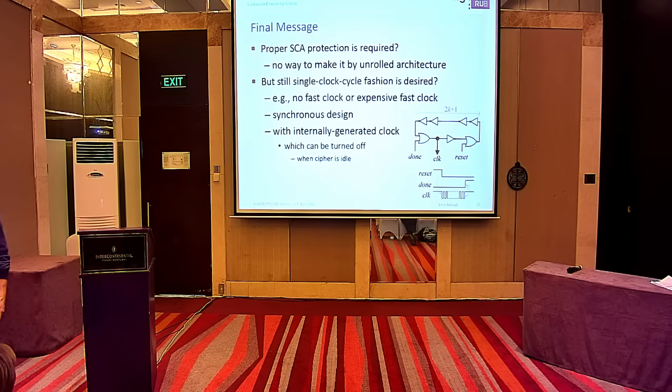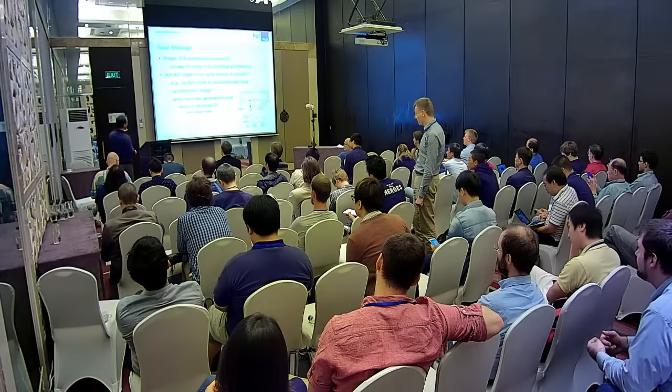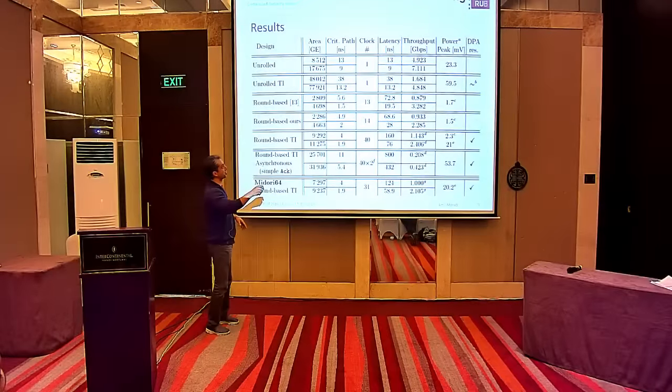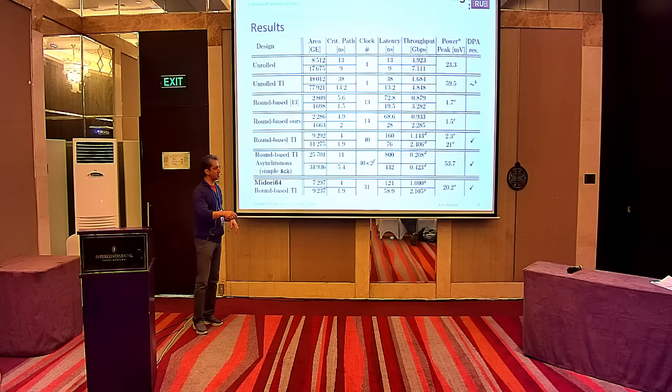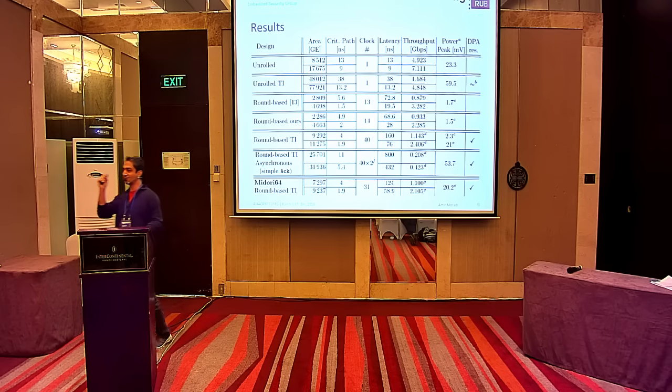It doesn't matter if you have a higher clock frequency, right? No, it matters. Sorry, wait a second. Here, the latency is the number of clock cycles multiplied by the critical path delay. This is 31 multiplied by 4. This will be the latency, not the frequency itself.